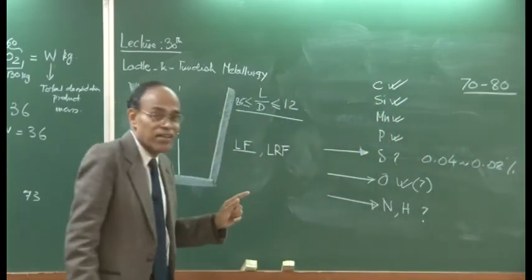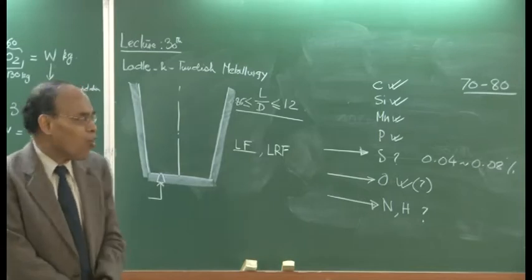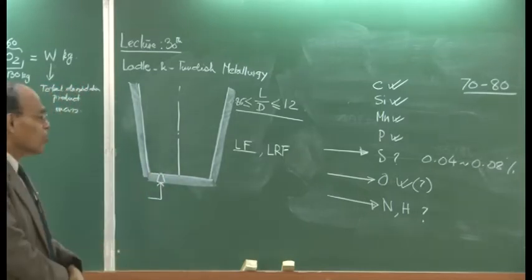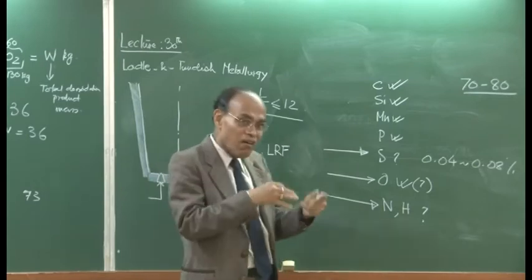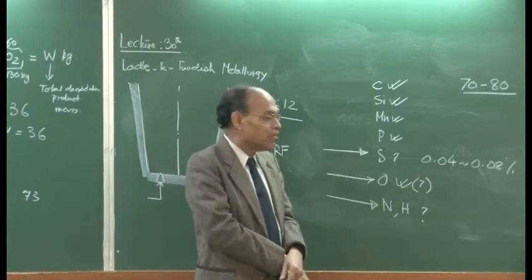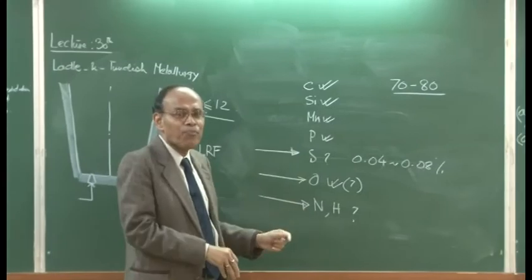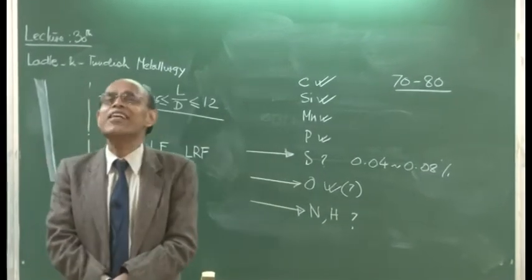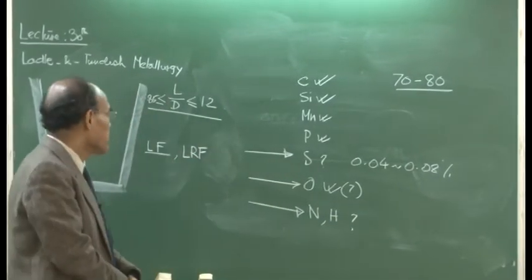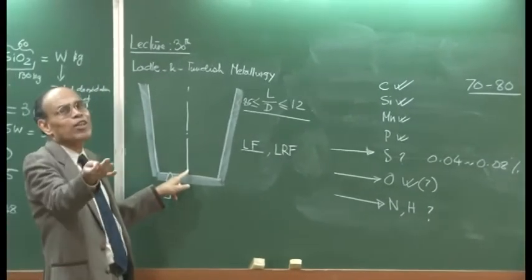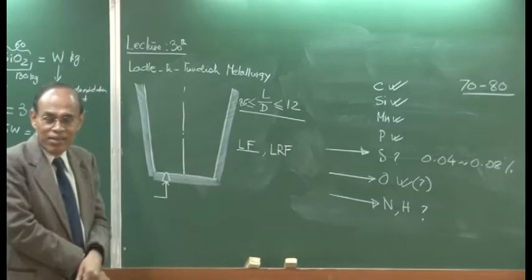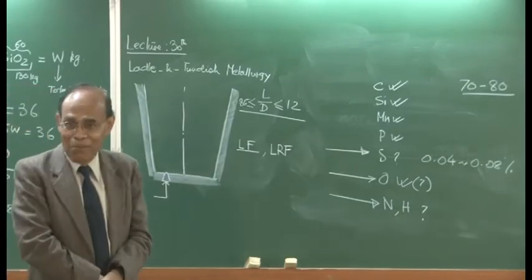And we must understand that for every steel all these treatments may not be necessary. Okay? There may be some cases where if you can carry out the BOF operation correctly, and deoxidation also completely, and you are not too bothered about the cleanliness of steel beyond a certain level, then the crude steel itself can be converted to a solidified product and sold to the market, but certainly not for critical applications.